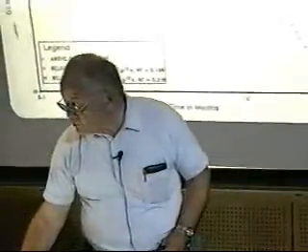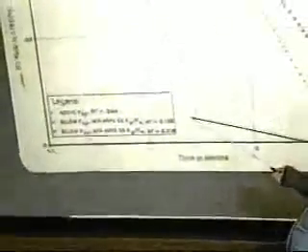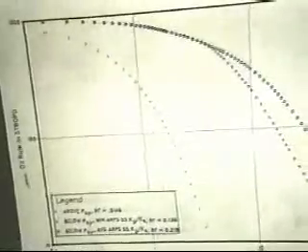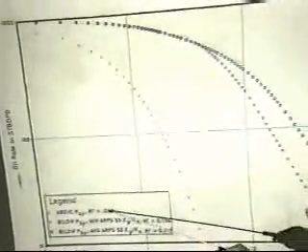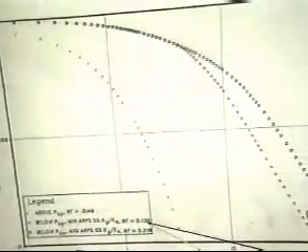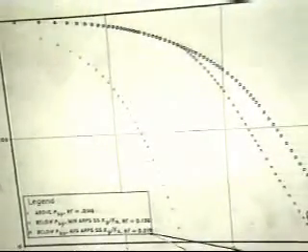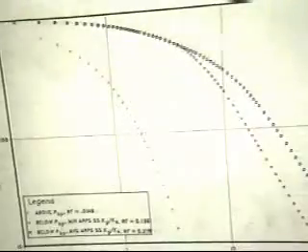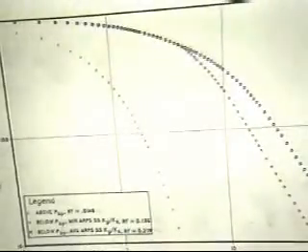We ran this case kind of as an extreme case to also demonstrate it in an undersaturated reservoir. This is where it would be extrapolating to, and these are the other two relative perm, the minimum and the average. This recovery factor would be about 1.5%. This would be 13% for a minimum and about 22% recovery factor for the average relative perm curve.